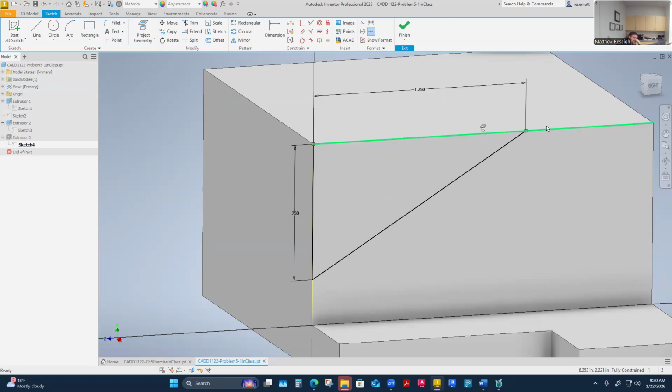And then, like I said, if I had this as a construction line, then this would not be a profile that we recognize to be cut. And in fact, I'll do that. I'll just turn that off for just a minute, because normally I would have. It's funny that I left that one solid, even though that's not my normal practice. Normally I would have turned that to construction. If I do this, I should get a blow up though, because I've now lost a solid line. So this extrusion should feel lost.